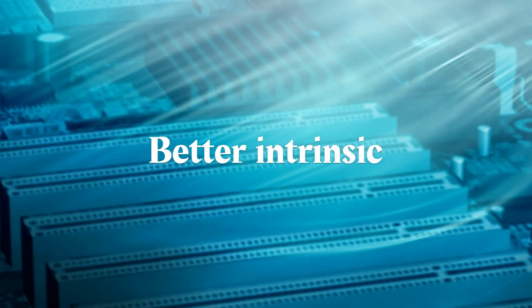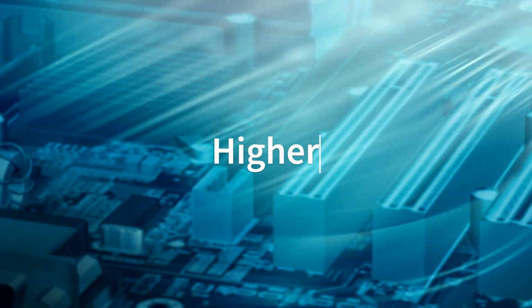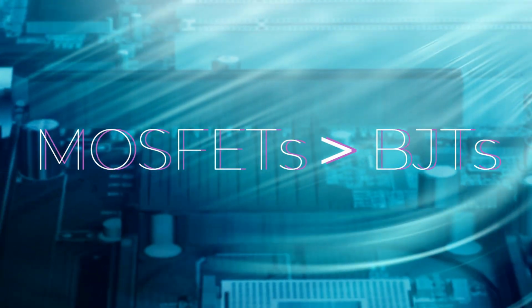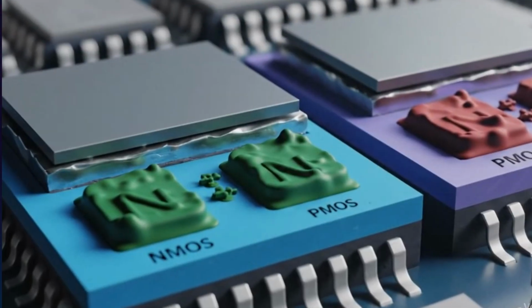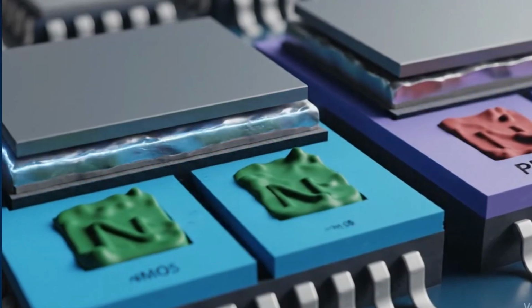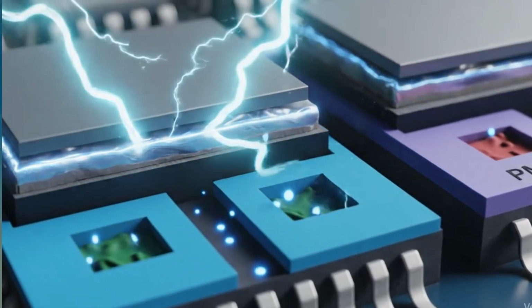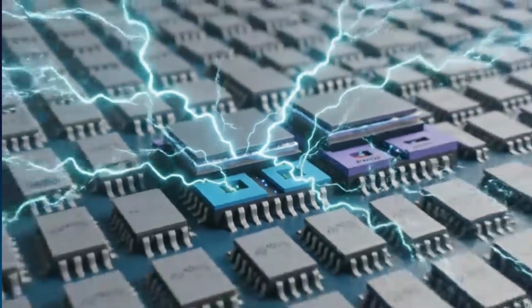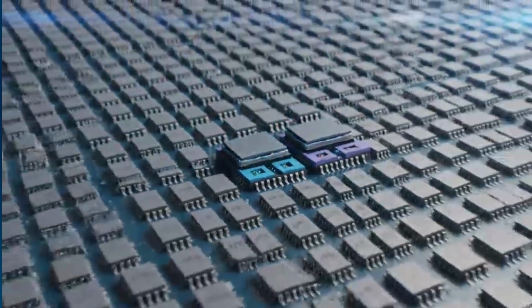Although BJTs offer high gain and better intrinsic speed in some cases due to higher carrier mobility, MOSFETs dominate in modern ICs, especially for digital applications. Why? Because MOSFETs leak less power, crucial for large-scale integration and battery-powered devices. They scale to smaller nodes, sub-micron and nanometer technologies, and have higher input impedance, meaning almost no current flows into the gate,